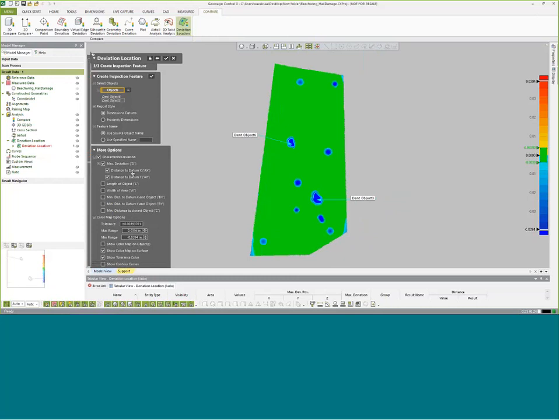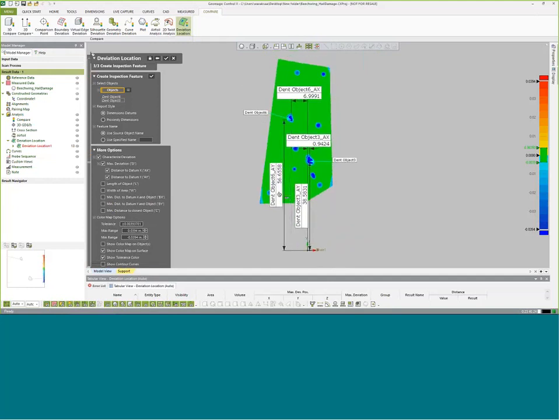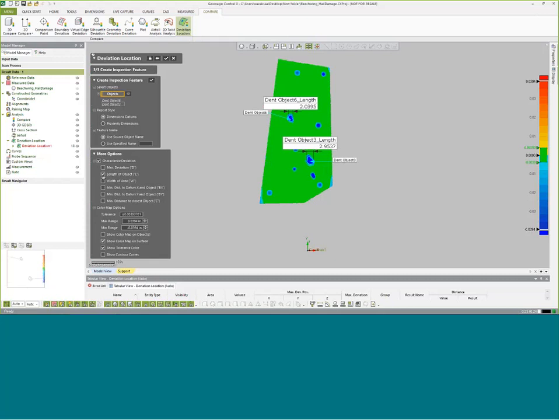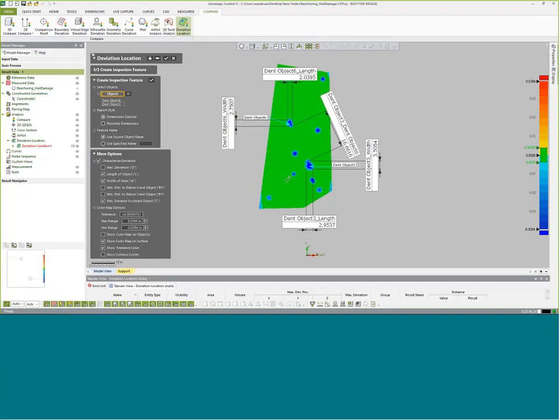So these measurements will relate back to where our coordinate system was based. So you can see that they're measuring from back where our coordinate system was, so we can classify things there, the distance of where those objects are based on that, and it's measuring to essentially the deepest point, like the center of mass of where that deviation is. If that isn't really of interest to us, we could always say maybe we just want the length and width of the objects, maybe a certain size is something we want to flag, so we could pull tags out to specify that stuff. We can still throw that minimum distance on if we want to between the objects. And we can really just set up whatever we like going into it.